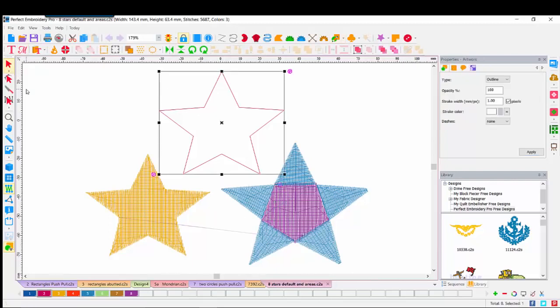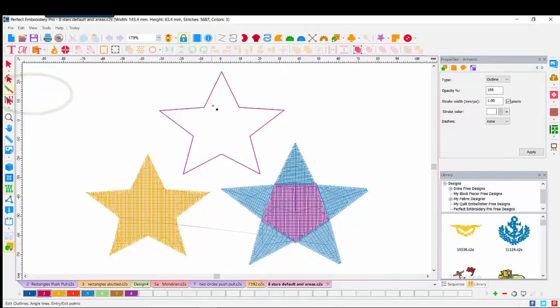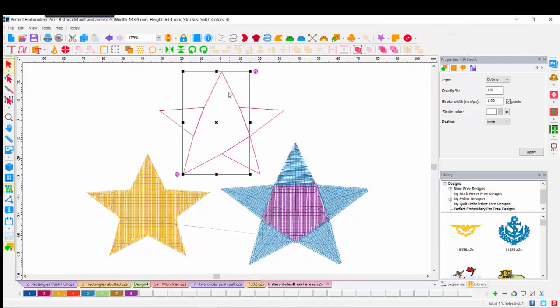To refresh, we've seen this before in other videos and webinars about the slice tool. We'll go ahead and choose the slice, and I simply then clicked and dragged to where I wanted that slice to happen. I'll do a click and drag and a click and drag. I'll do those three first. A right click on my dot, do an update path, and I can come up here on the toolbar to break apart, and those are separate. I'm left with this middle area.